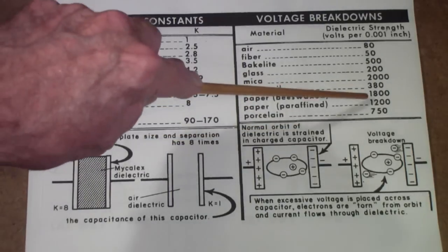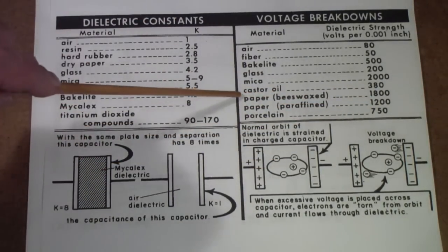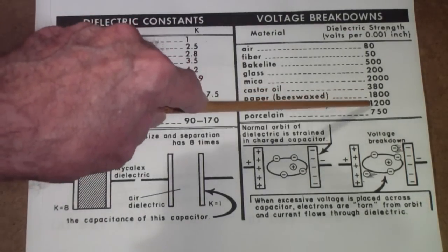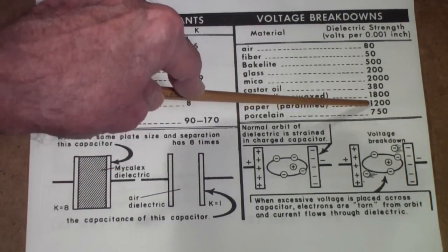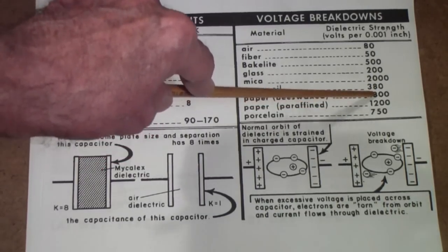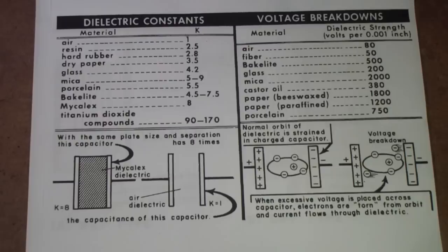But as you will discover when you begin to look at some of these old radios, paper, as I said earlier, deteriorates. So even though this is the rating when the capacitor is made, it may wind up being 800 volts or maybe only 80 volts by the time you get the radio, especially if the radio is 60 or 70 years old. So once again, I hope this has been useful material, and I hope that you find it helpful as we go forward.